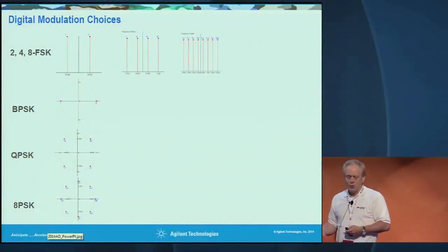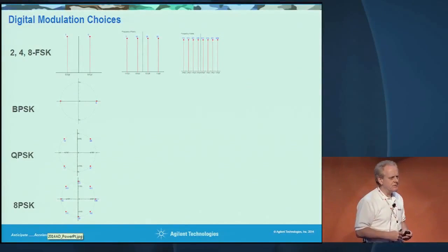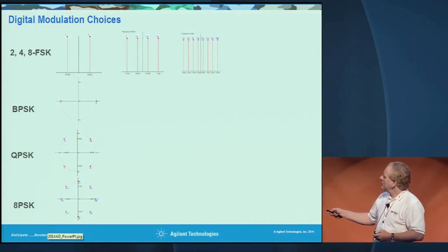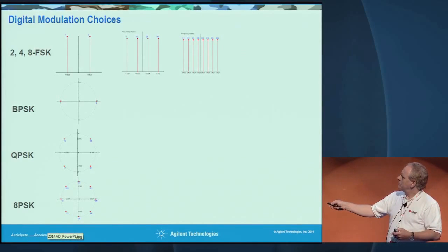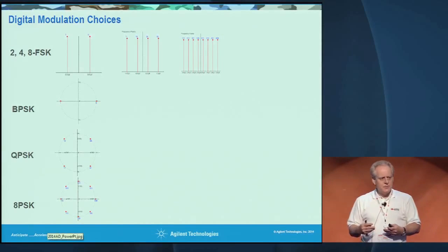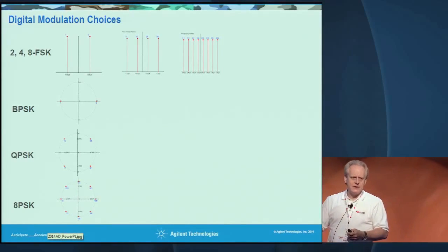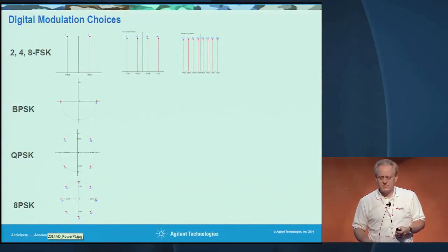So in older formats, they would generally use more simple modulation schemes. Here, BPSK is pretty bulletproof. It will go between two states. Generally, because of the limited power, you're using a constant envelope type of modulation system.